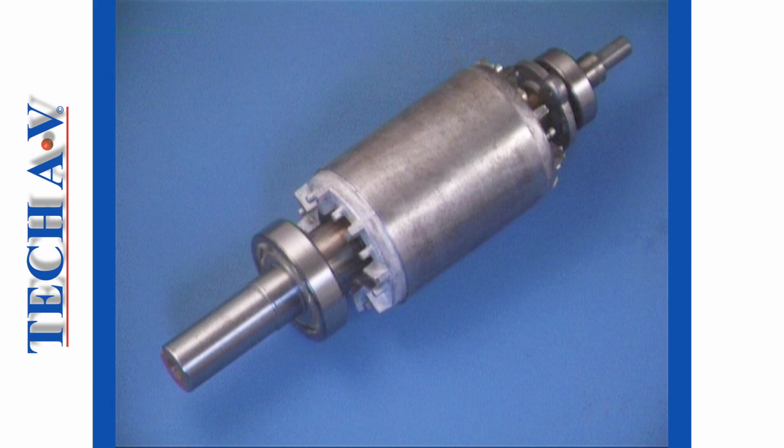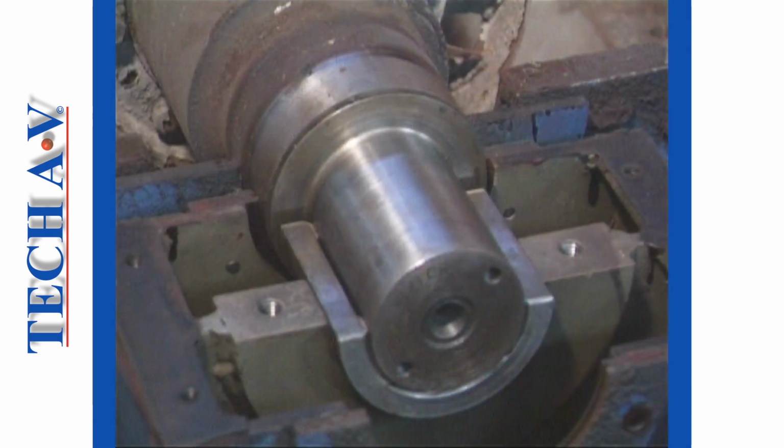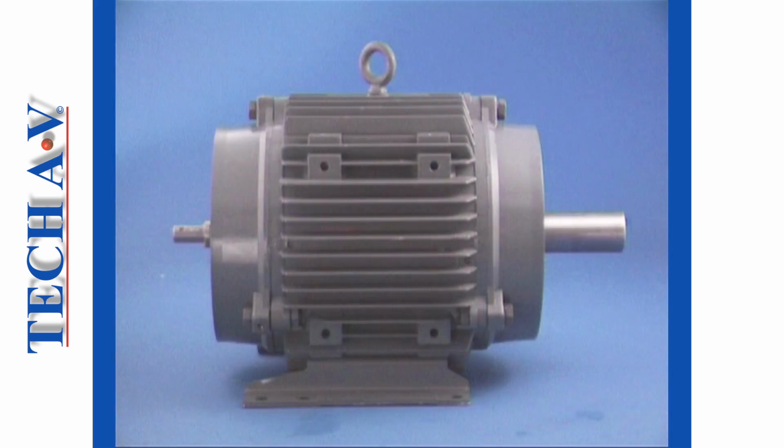The rotor plays an important role in the motor. The rotor and its shaft are responsible for the transmission of mechanical output. The rotor is supported on bearings, usually in the form of ball or roller bearings. Some motors, however, have plain or sleeved bearings, more common in the larger kilowatt ranges. End shields provide the means to support the rotor. The bearings are housed within the end shields. When secured to the frame, the end shields support the rotor in the correct position within the frame.